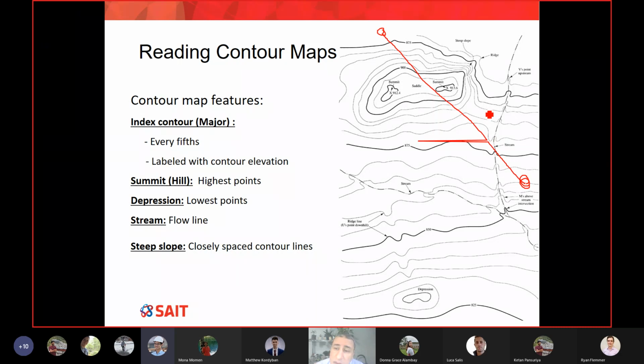We would need a bridge. You can see that if I do so, I'm kind of climbing on top of the mountain and then going back. I think this is not a good idea because you will have lots of cut and fill. To do a good job, you can make an alignment that avoids this and simply turns around the mountain and then connects to the other point. Please forgive me for the spikes. Whenever I press hard on my pointer, it just makes a spike.